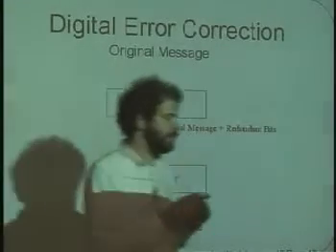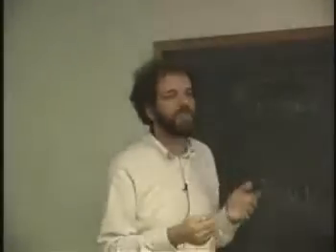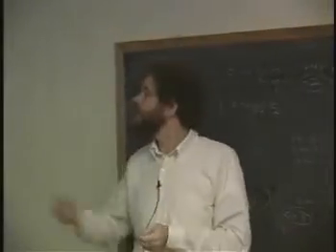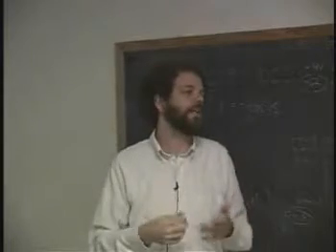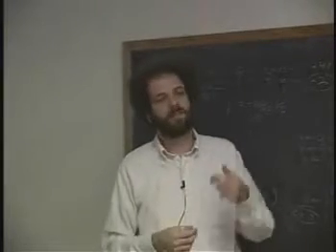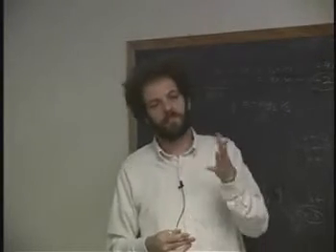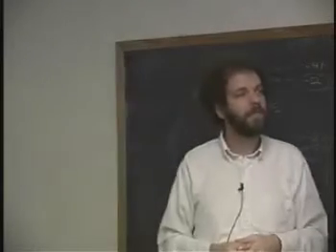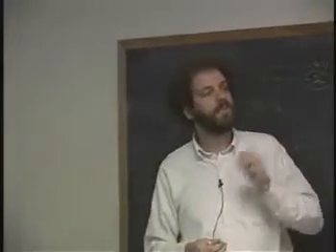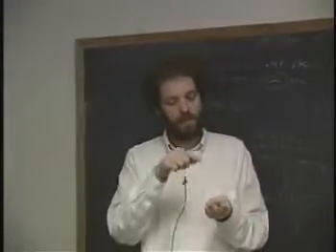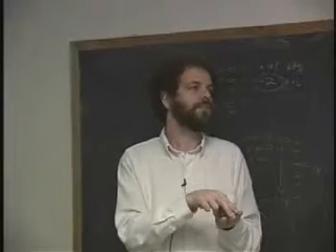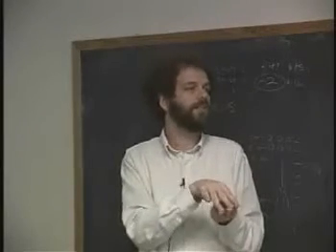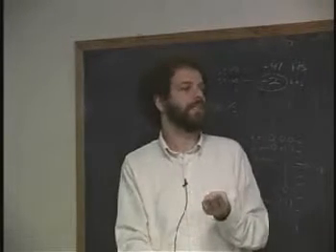And there's a whole science to how to design those two things. A very simple one you might want to think about is take every bit that you get in and replicate it. For every bit you get in, send 2 bits out. Okay, it turns out that's kind of an inefficient one, but what if you do it every bit you get in, send 3 bits out? That way, if any one of them dies, you can look at the other two and just take a majority of every 3 bits to determine the 1 bit that gets out.